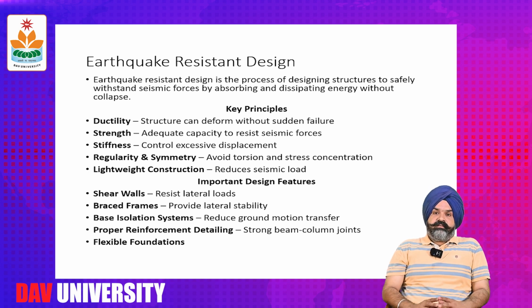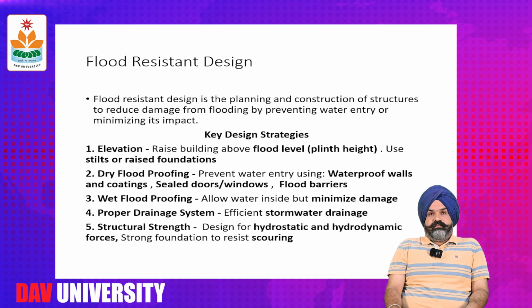Now we are discussing earthquake resistant design. For designing commercial, residential, or any type of building, these are the key principles that must be incorporated in the design: ductility, strength, stiffness, regularity and symmetry, and lightweight construction. And important design features are shear walls, brace frames, base isolation systems, proper reinforcement detailing, and flexible foundations.